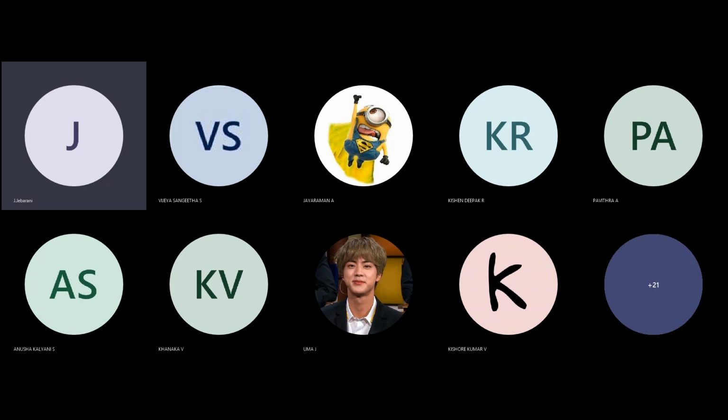The mold is turned from side to side to receive the two or three injection streams, one after another, from the injection nozzle. The product frame is built from the beginning and filled with each color resin at the selected area.